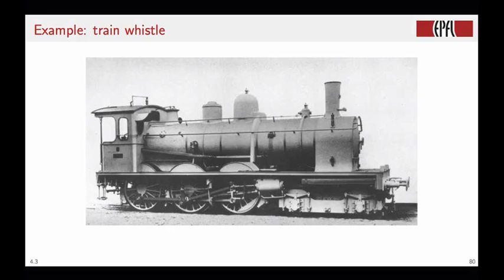Suppose I give you an audio file that records a train whistle, and I'm asking you to find out which notes make up the whistle. And of course your idea is to take the DFT of this file and find the peaks in the Fourier transform, which will probably correspond to the fundamental frequencies of the notes that are being played.